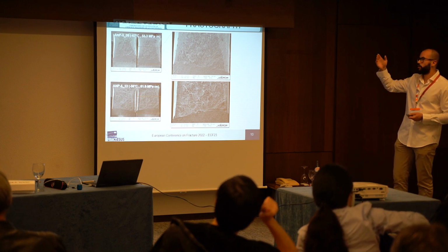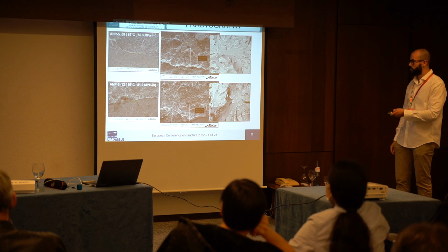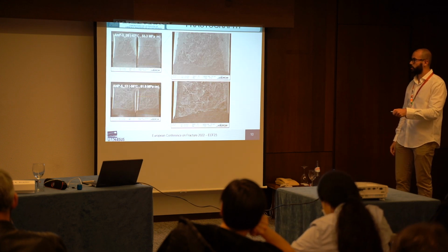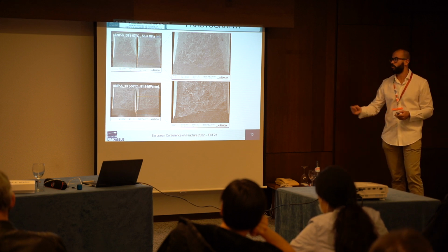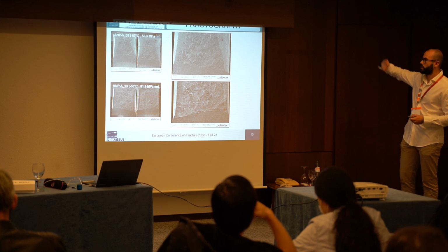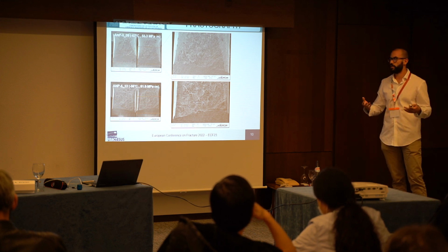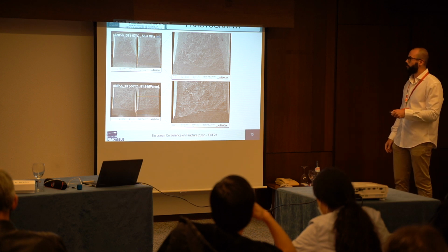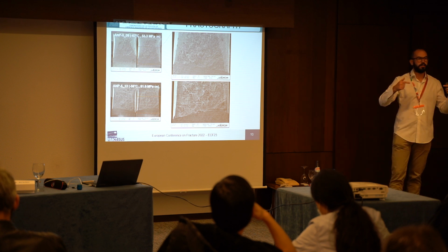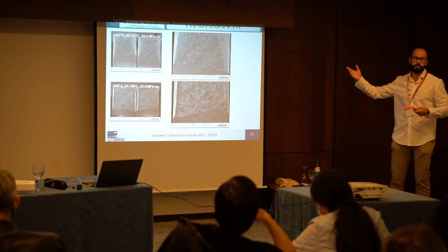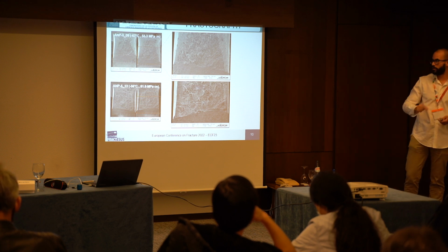The most important thing is that at the beginning, a small ductile area is present with microvoids, and then the rest of the surface is flat. The main mechanism is clear. Also, it's remarkable that we have some slant fracture at the edges of the specimen, mainly due to the plane stress effect.